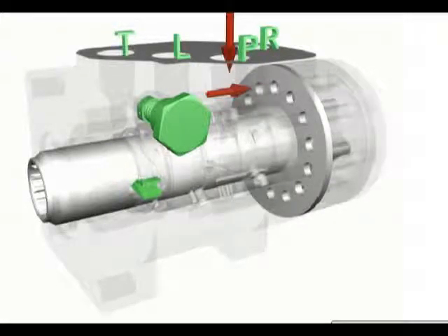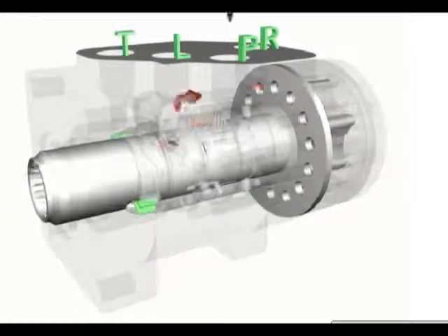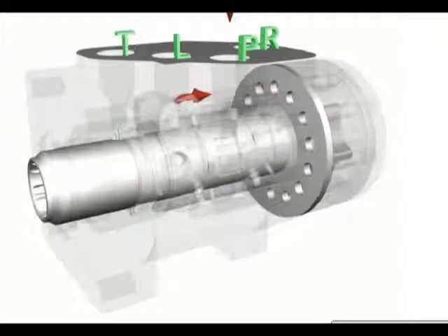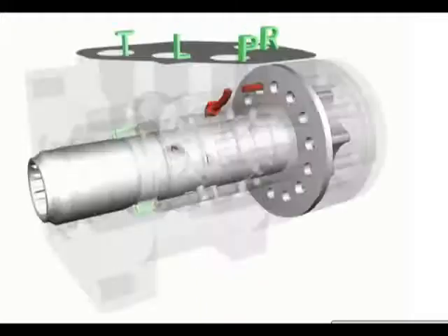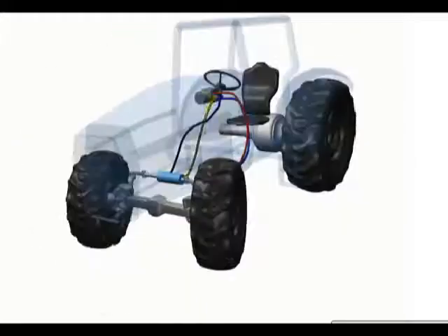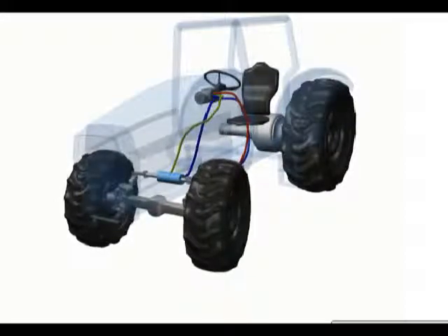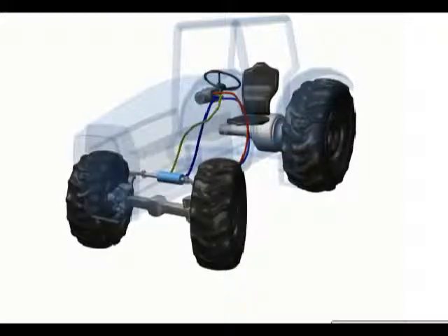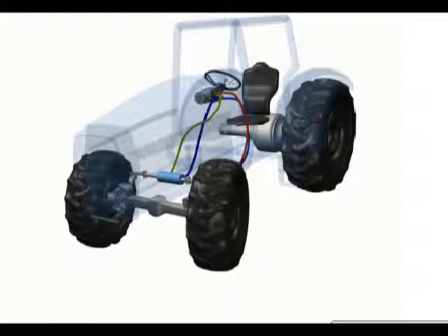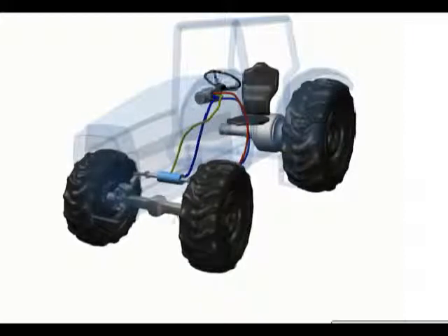Rotation of the steering wheel clockwise reverses the flow path through the unit and turns the wheels in the opposite direction. Pump flow not used in the steering circuit passes through the tank port of the unit to the reservoir and to other downstream functions through the